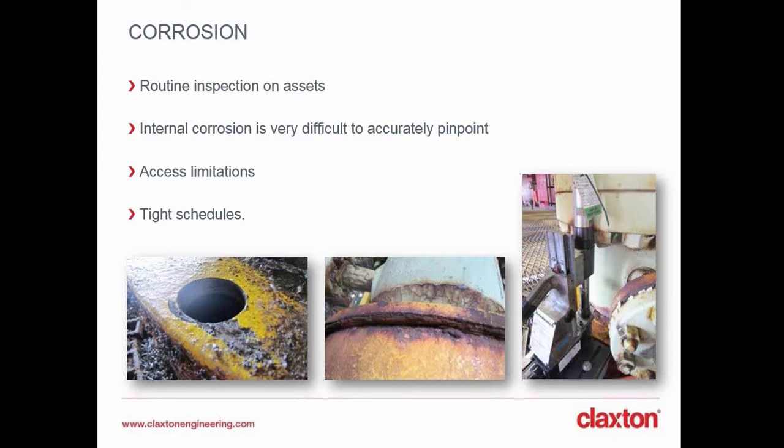In summary, inside out is less favorable due to the inability to inspect casings to verify they are fit for long-term service, and the inability to properly prepare for remedial work. You can potentially have problems if they're cemented. Outside in will be favored due to the ability to visually inspect all casings, suitability for long-term use, and the ability to handle cemented casings as well. So overall, potentially the shortest projected time frame to complete the whole work scope, and with the highest chance of success and safest option.